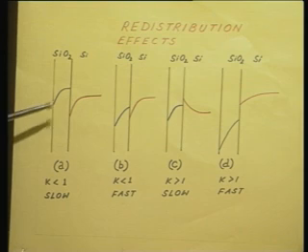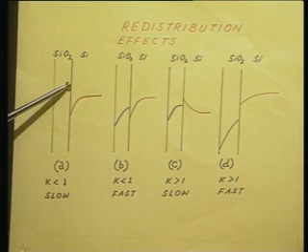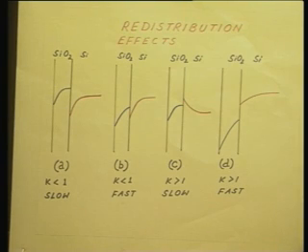Boron has preferentially come inside the oxide. So, this increased presence of boron in silicon dioxide is going to affect the diffusion of the oxidizing species through the oxide. It is going to aid in the diffusion of the oxidizing species, because now you have a silicon dioxide which is heavily boron doped.